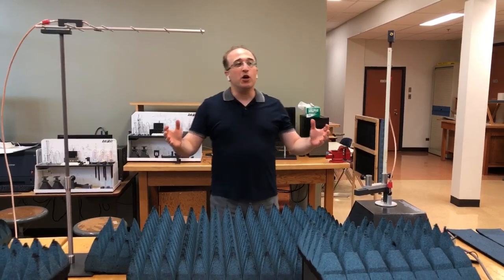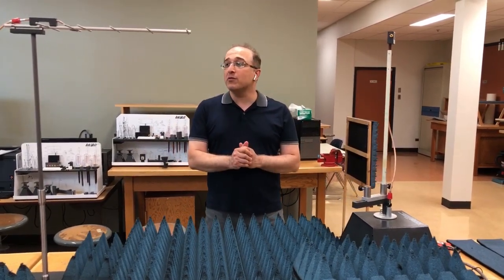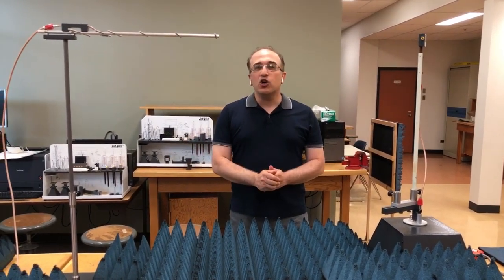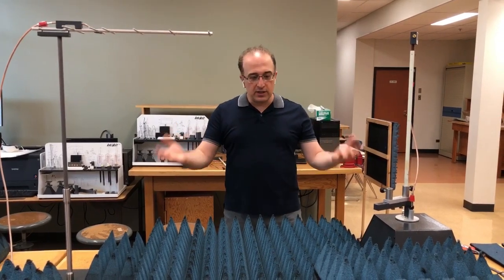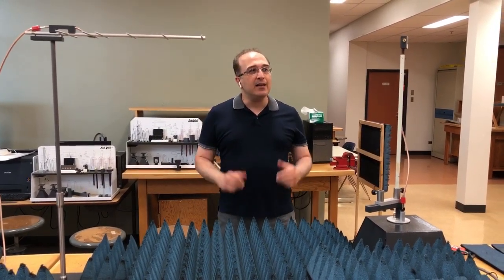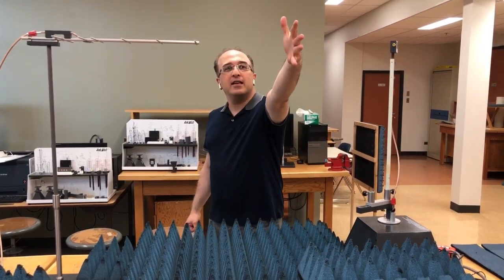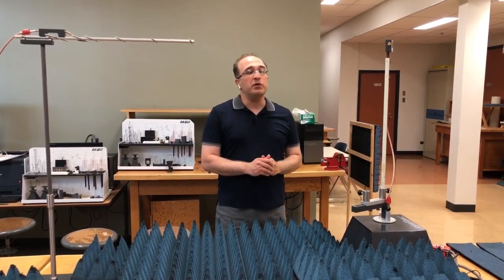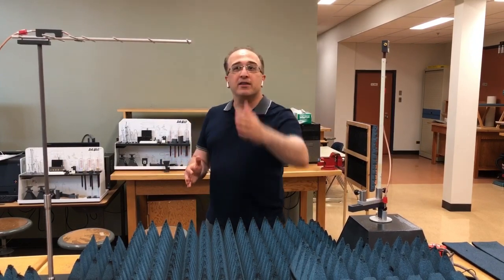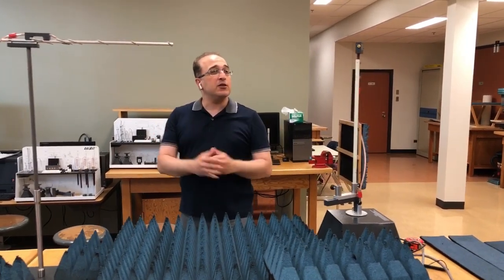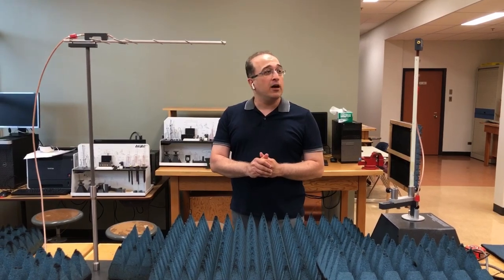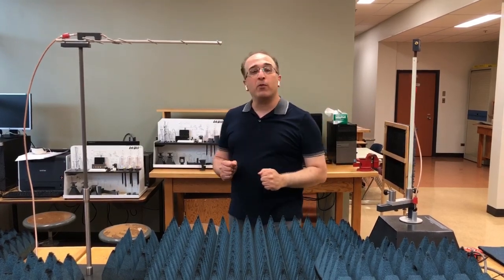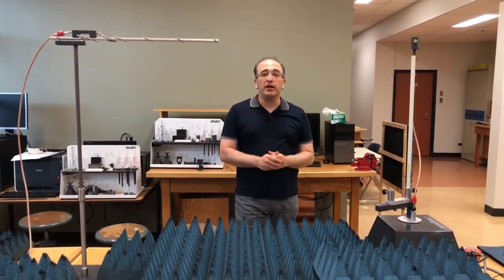In this experiment, we're gonna perform two different types of acquisition. The first acquisition would be simply the E-plane cut of a half a wavelength dipole antenna. So this would be the system that we are using. The second acquisition, I'm gonna place my hand here and I'm gonna perform another acquisition. So we're gonna see what would be the effect if I essentially have an object between the antenna under test and transmitting antenna. So I'm going to place my hand like that, and I'm going to perform another acquisition, and then we can compare these two acquisitions.